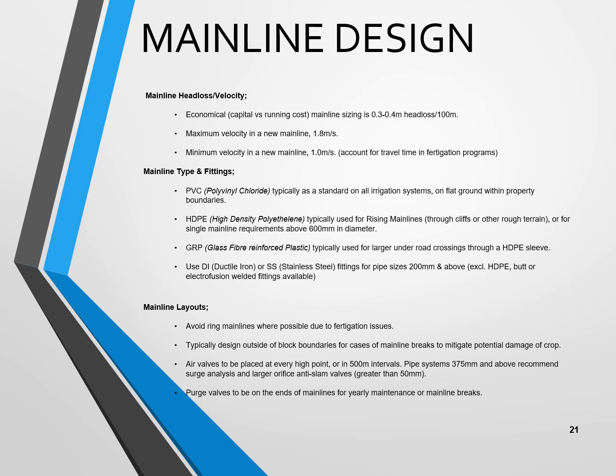The use of ductile iron or stainless steel fittings on any pipework above the size of 200 mm is preferred. This excludes HDPE, as we have butt or fusion welded fittings available for these sizes.